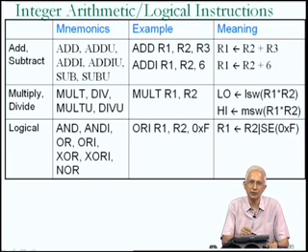So there is an add instruction which can be used to add integers. Add u, which we understand stands for add unsigned, so from which we infer that add must refer to adding of signed integers. Add I, we know that I stands for immediate, so this is add immediate. Add IU, which must be add immediate unsigned, and then corresponding subtract instructions such as subtract and subtract unsigned.